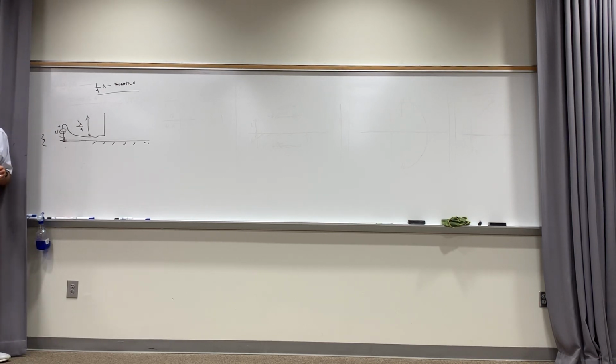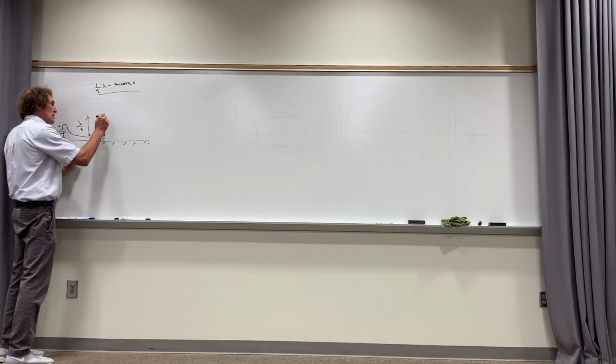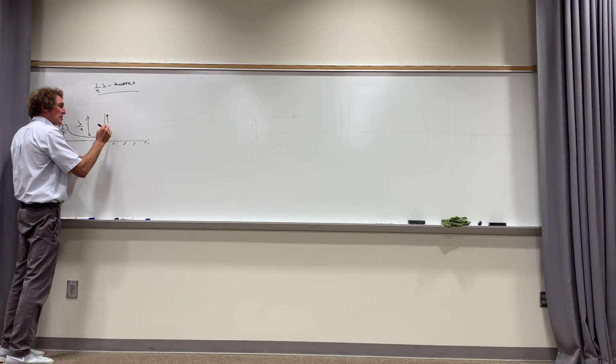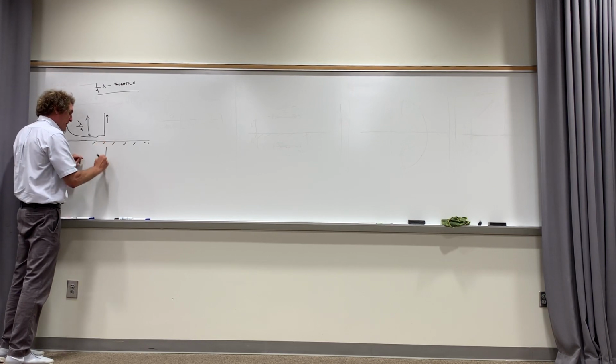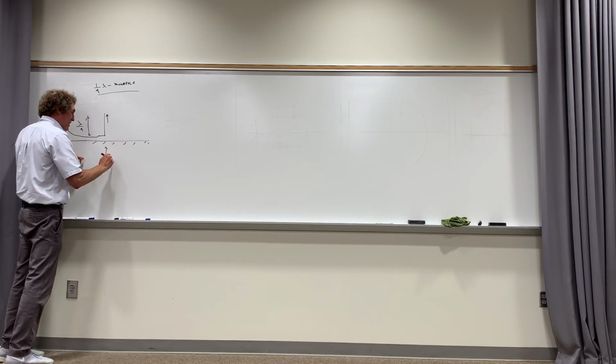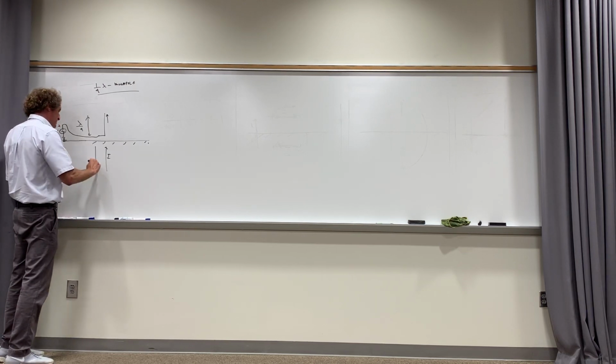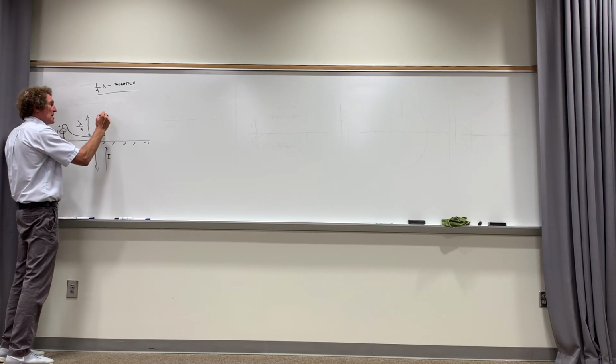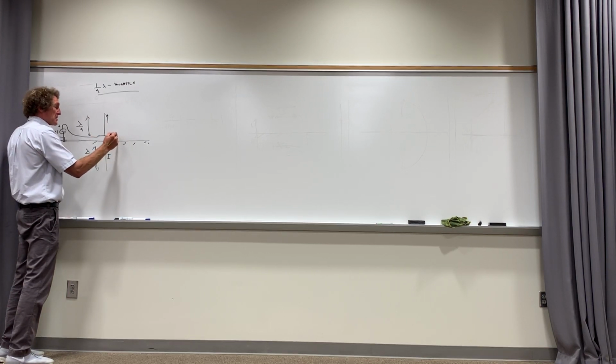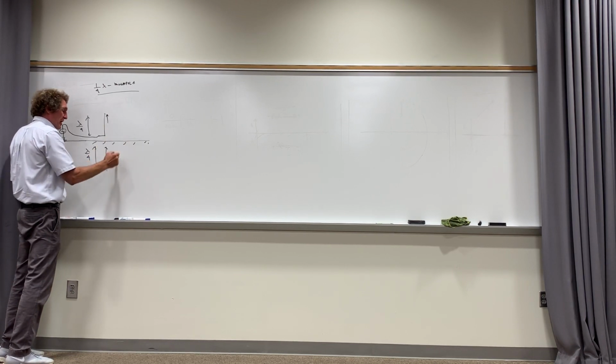Now, you can see one advantage is it's half as long. What would happen is there would be a current flowing here, and we know there's a current on the dipole, but we would have an image current here. That image current would be of an extent of a length lambda over 4, and it would have the same current signature. If the current here looks like a quarter wave dipole, it would look like the actual current distribution of a half wave dipole.